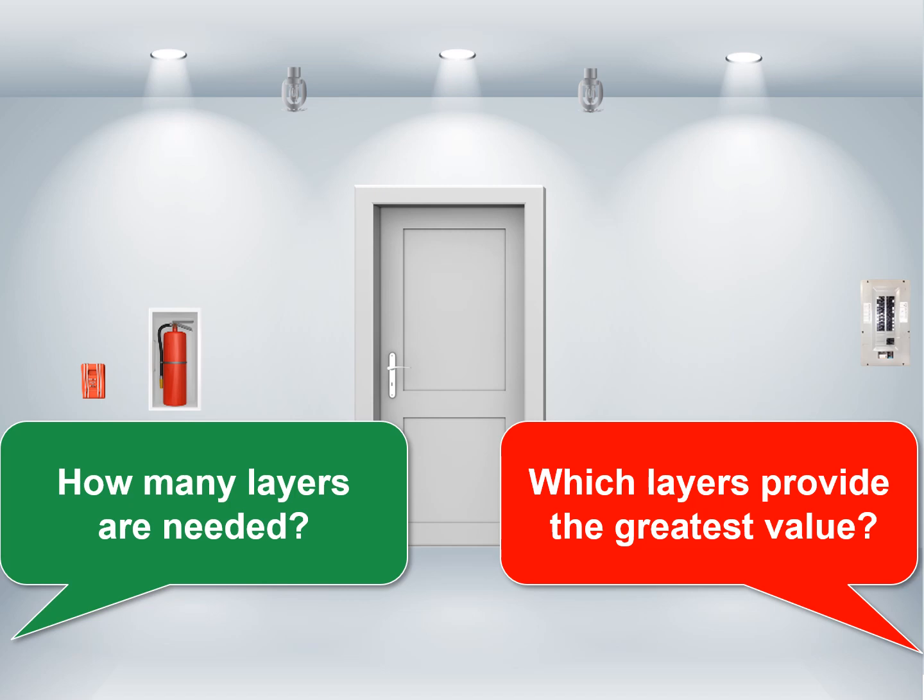Maybe sprinklers are at the top of the list, but fire-resistant construction will allow interior fire suppression operations should the sprinklers fail. Fire separations will allow protect-in-place strategies where needed, and a smoke exhaust system will add to the allowable egress time. All have a role to play depending upon the building or facility being protected.